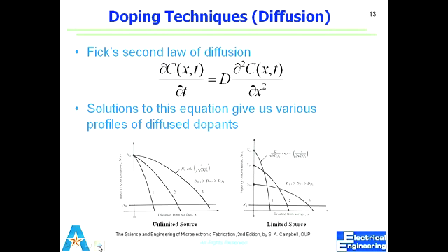So if this is the top of the wafer, and I look at concentration, I'll have high concentration, it will fall down, right? If I keep on supplying unlimited source, this is going to diffuse further. But if I have limited supply, whatever I incorporate at the start is going to become diffused over more distance from the surface. So it makes sense?